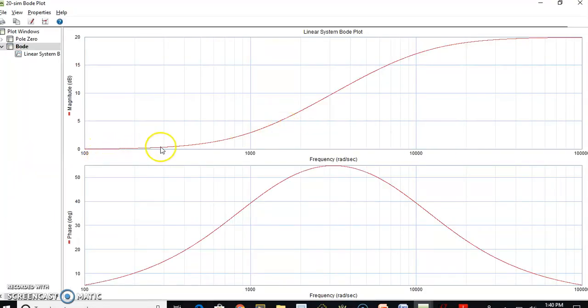per decade, and then the slope increases. So at exactly 1000 radian per second, we're going to have the 0 located. So because it is 0, the slope is going positive, and it again becomes flattened, that is 0 dB per decade, because of the presence of a pole. First a 0 comes, that's why positive slope, and then a pole comes, so that whatever plus 20 per decade will be nullified by having this minus 20 per decade, and it again becomes 0 dB per decade.